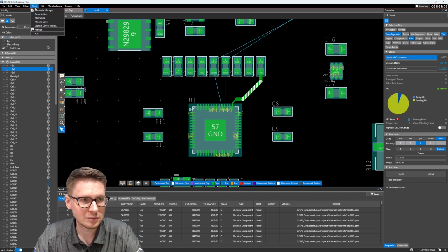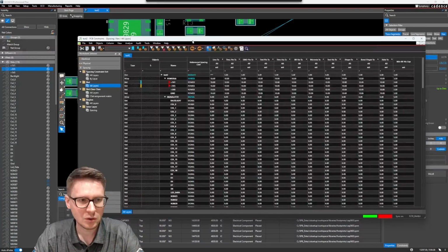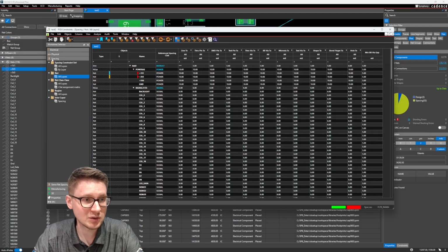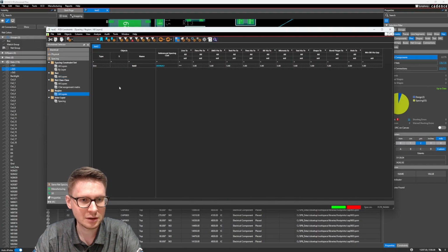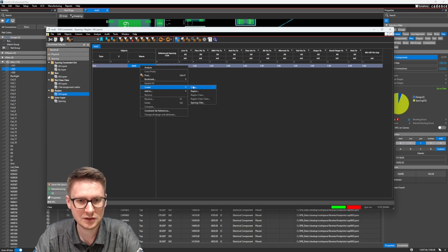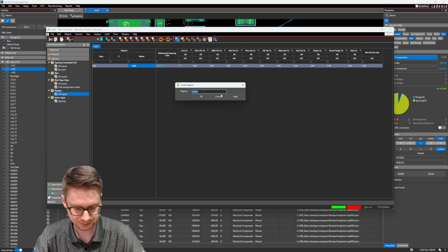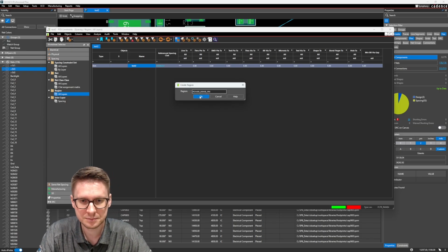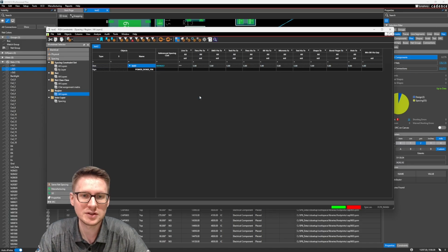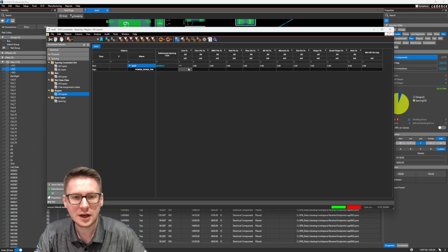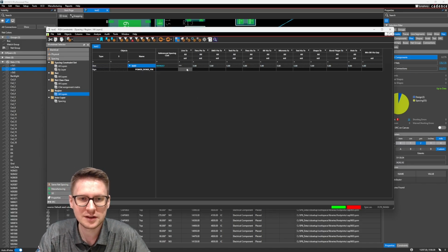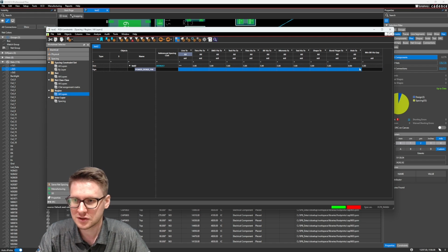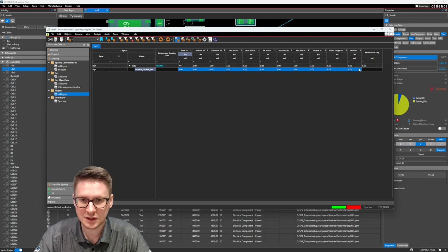So to do that, in Constraint Manager, we will go in the spacing worksheet to Region, All Layers, right-click, and select Create Region. And we will call this our Power Dense Pin Region, or use whatever name is descriptive for you. And in this region, we will say that it is okay to have, across the board, 6 mils.